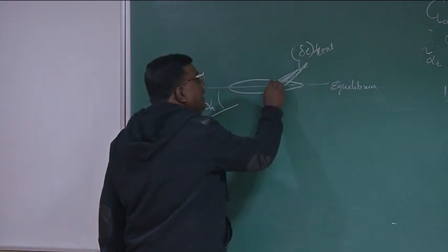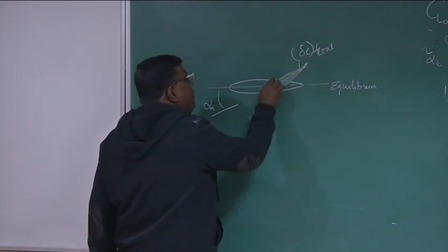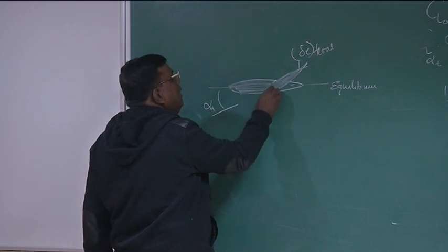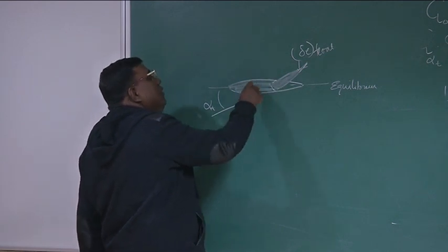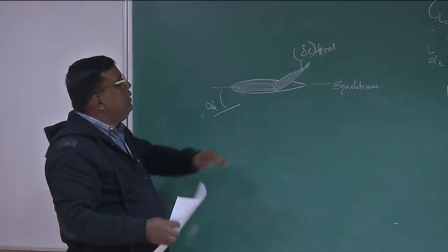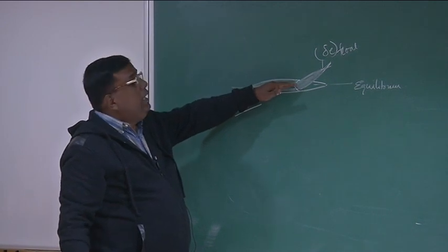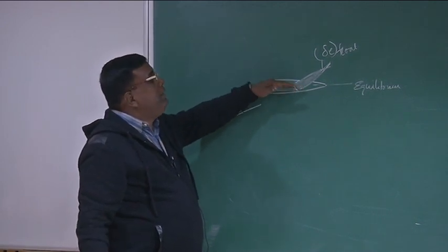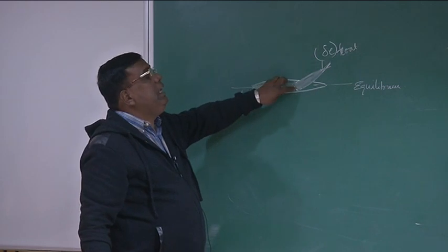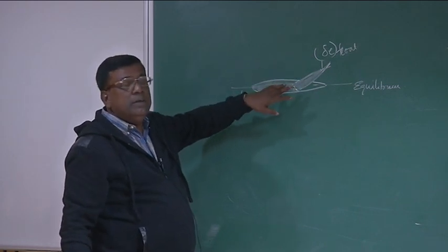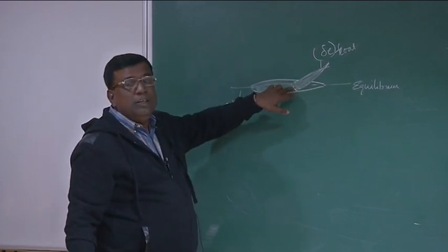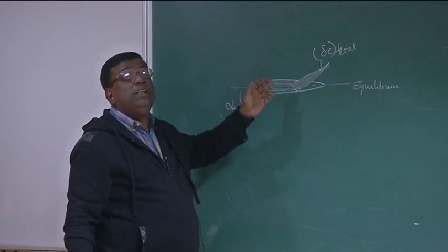So now if I try to move the airplane from this configuration to another, I take this as an equilibrium, and you could see that since it has floated up, its CL alpha has to reduce compared to the first case. If you do a camber, it will further increase.